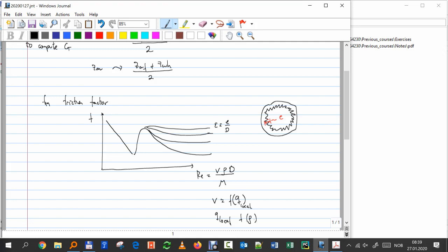The thing is that for gas, first, velocities are very high compared to liquid. What can be a typical liquid velocity on a pipe, on a well or a pipeline? For example, for liquid or oil, we are saying velocities maybe someplace between 0.5 and maybe 4 meters per second.